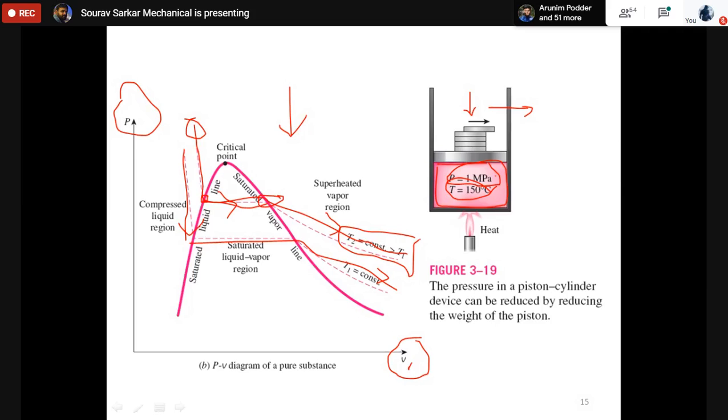It's not absurd. Whenever you have a pump, there is a suction inlet. In that suction, the pressure is sufficiently low so that water at 35 degrees Celsius will start to boil and form small bubbles. These bubbles will collapse, and that is detrimental for the whole system. That is why I am saying these things are common.